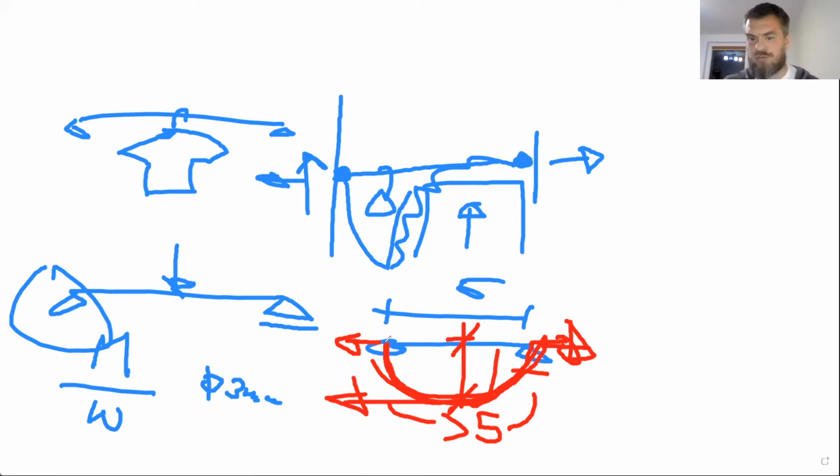The model deformed, the string did only one thing, it bended downward. And this bending elongated the string. This elongation caused normal force in the string, tension, and this tension was the thing that made the string survive. This is why it would fall off from the table here, because there was nothing preventing this horizontal movement.